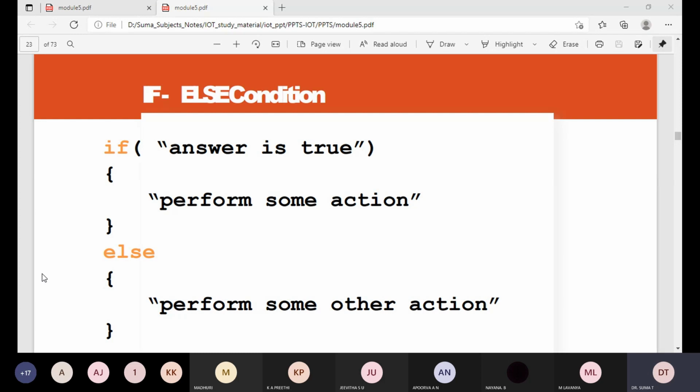Pulse width modulation pins are also digital pins, so they output either 0 or 5 volts. However, these pins can output fake intermediate voltage values between 0 and 5 volts because they can perform pulse width modulation. Pulse width modulation allows us to simulate varying levels of power by oscillating the output voltage of the Arduino UNO. And see here, the analog and the digital voltage.